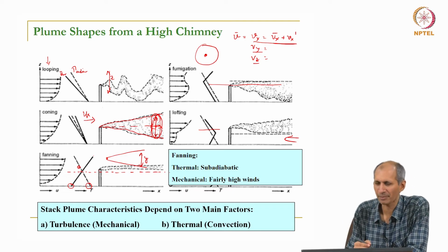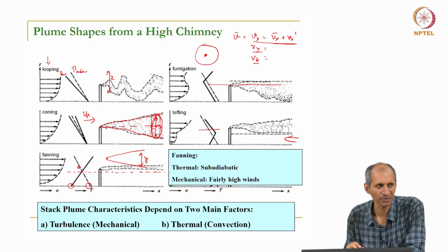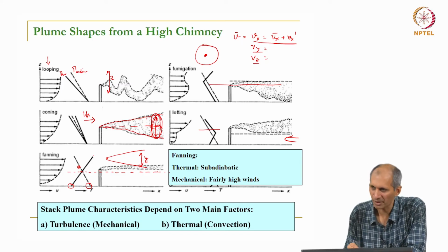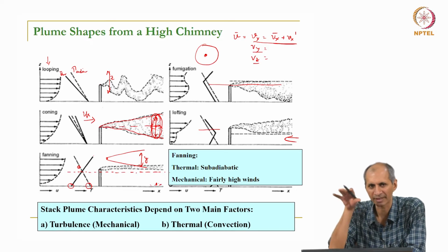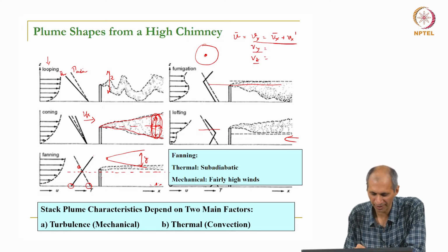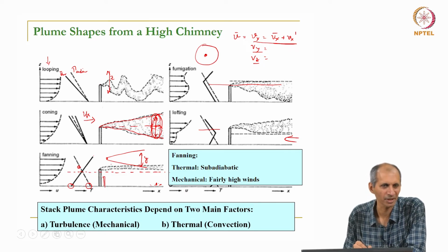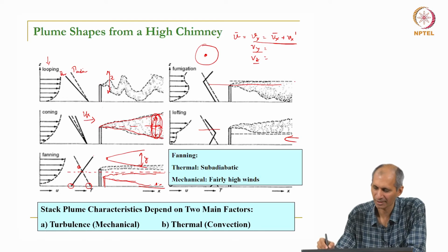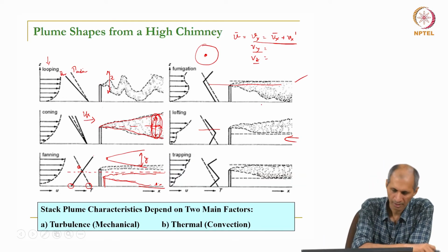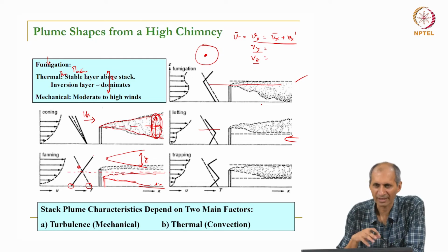But this is not really bad because from the point of view of exposure, if it is going to stay like this, your receptors are somewhere here on the ground, so it will not come down, it will stay there. This will be a problem if the source is here, below the mixing height. Then it will go up, then it has nowhere else to go, and mechanical turbulence will spread it like this. This is one of the cases we call fumigation, where it is exactly the opposite.